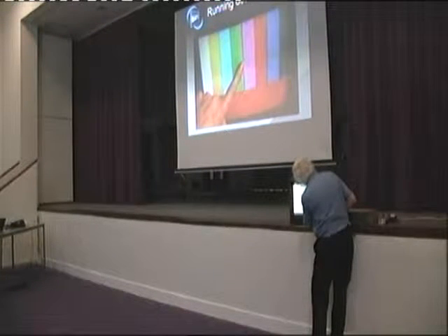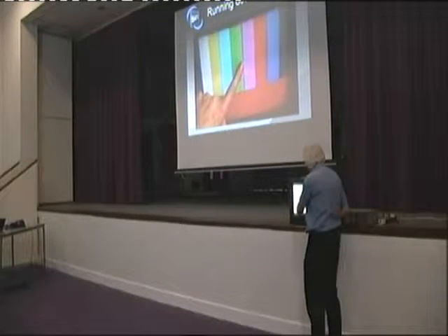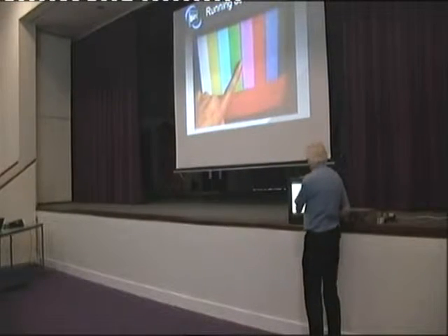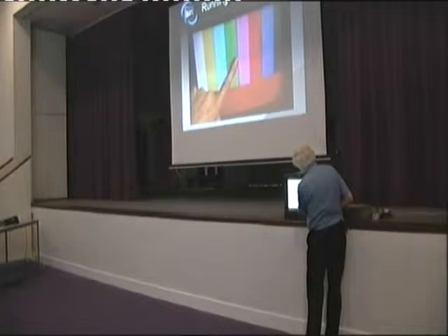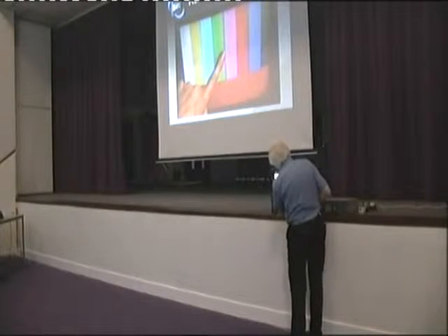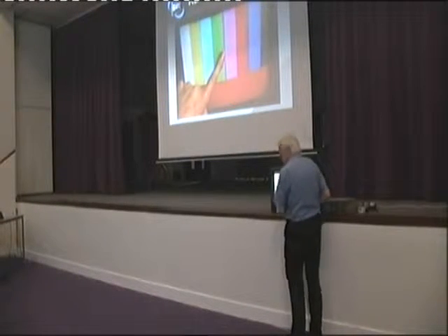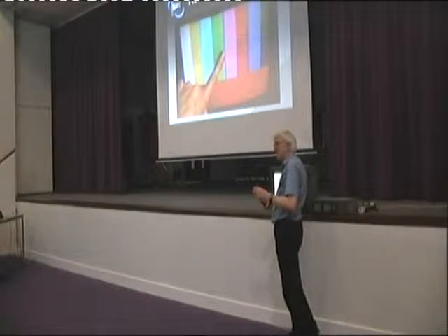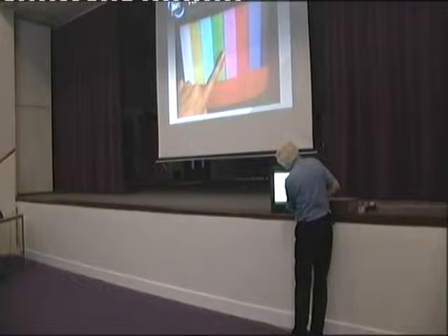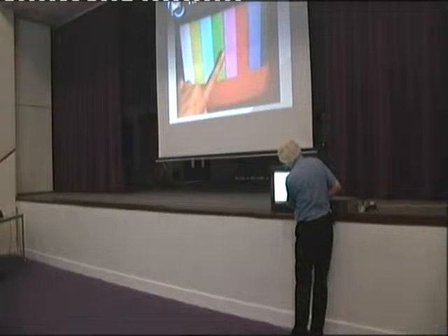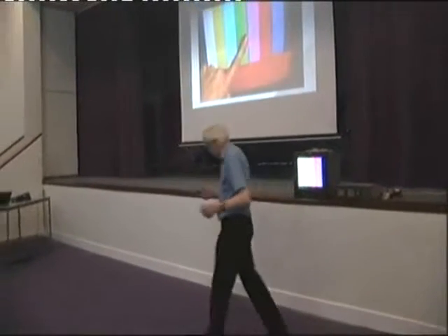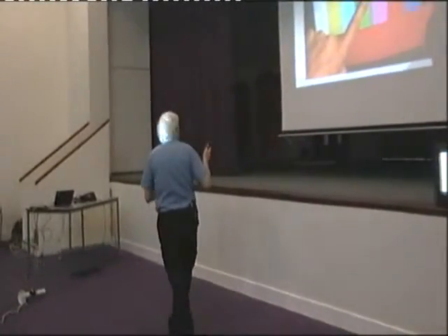Now, one of the things you can do with colour bars to determine if you have a proper mathematical signal is if you run your finger down here, the pattern follows. And it's a quick and easy test that you can do. That's about the right speed. And this is an SPG which I borrowed, and I'm pleased to say that it isn't mathematical PAL. Somewhere the numbers have gone wrong, because if I follow the finger up, the pattern is drifting up slowly when it should be drifting down at that speed. So that's faulty.